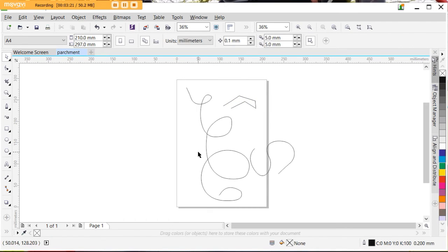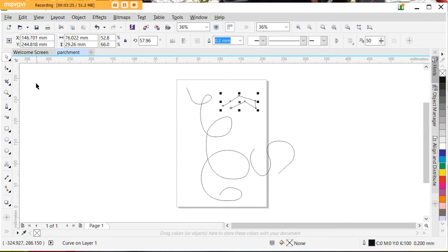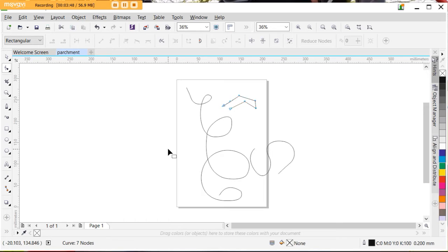If we want to do something a little bit more clever with it, if I just select it again, come to the next one down, and this one, when you see, is called the shape tool. And the shape, there's 2 or 3. If you look at the little arrow again, you've got the shape, you've got a smooth, a smear, a twirl, attract, repel, smudge and roughen. Most of the time you'll use shape. You might occasionally use smooth. We're going to stick with shape for the moment.